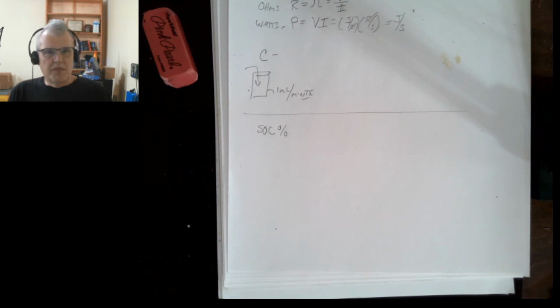So obviously most people, when they're building a Powerwall with 18650 batteries, are not going to go to 100% state of charge and then down to 0% state of charge. You're just not going to do that, because you can get many, many more cycles out of the battery. So you would want to cycle it very minimally if you can, depending on how much energy you need at the time.